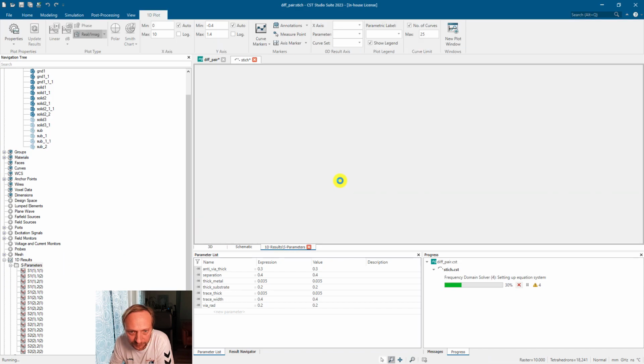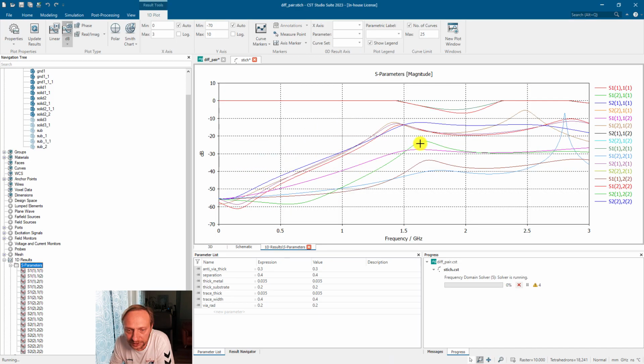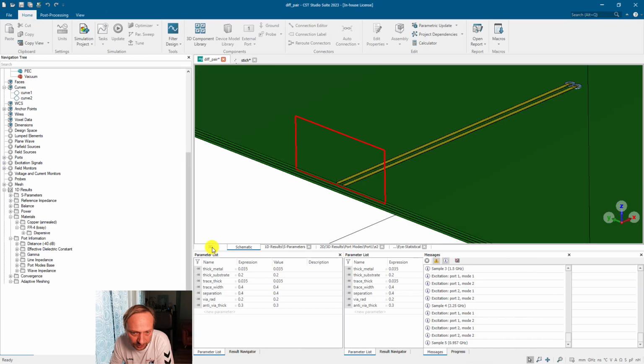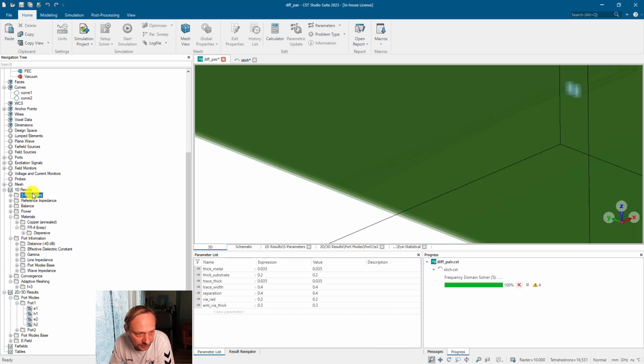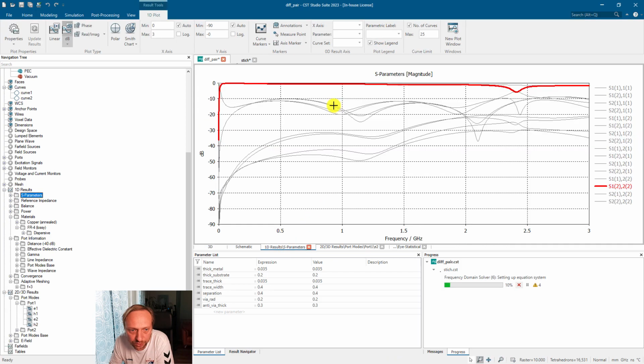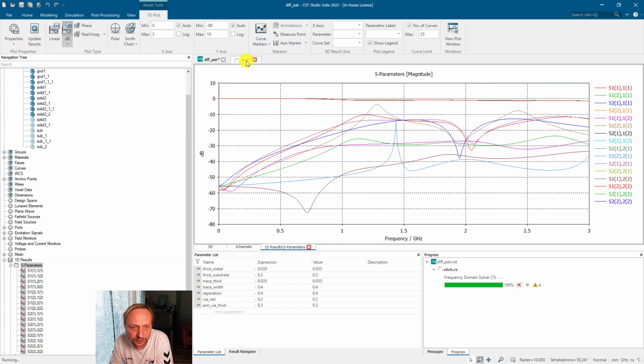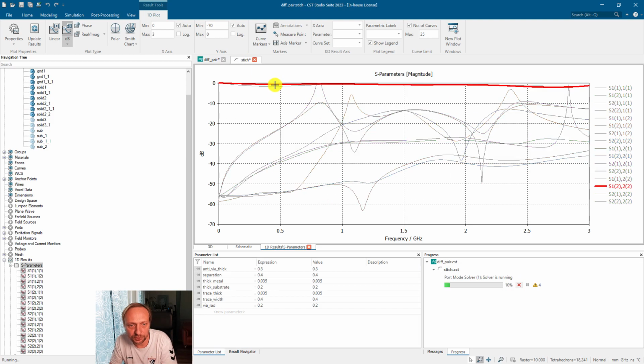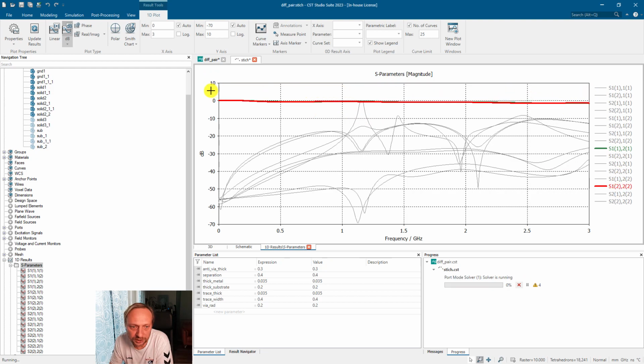So I go to the S parameters, which are still in the calculation. If we go back to the model without the stitching vias and look at the S parameters, you can see this was the differential mode transmission and this was the common mode transmission, which didn't happen at low frequencies. Now if we go to the stitched model, you can see both curves going up here, differential and common mode transmission, which is now happening due to me adding the stitching vias.